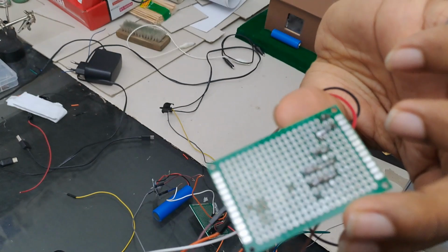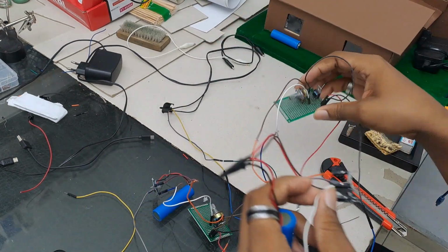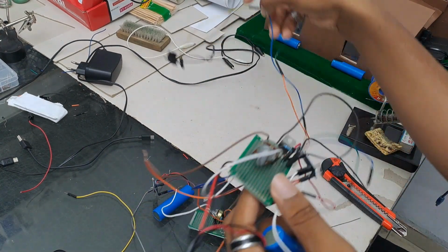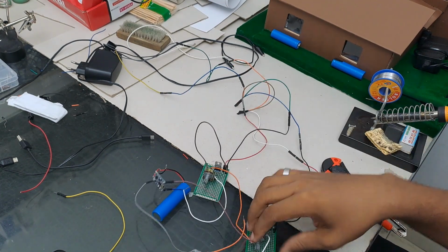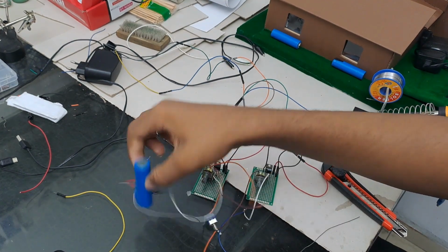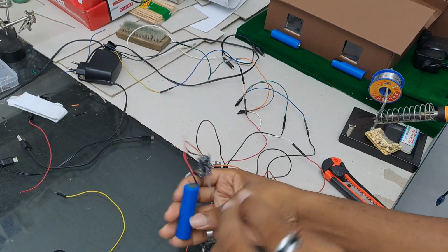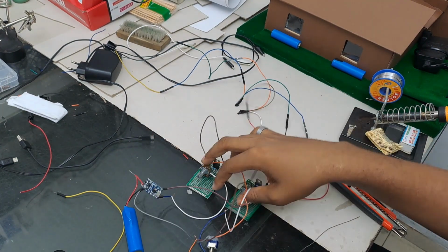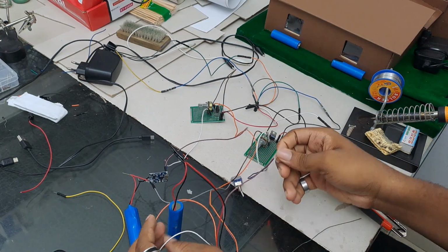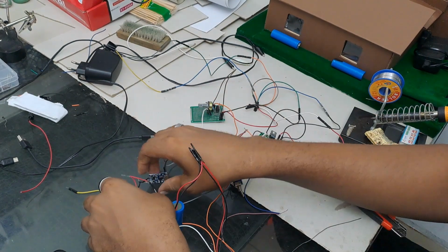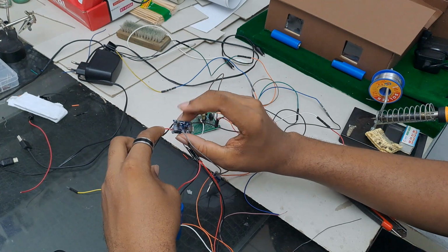But since everything is within the 5 volt and 3.3 volt range and should not be enduring any stress like an electric motor or a servo motor, where you would want your power externally supplied and your control pin to your Arduino alone, this functionality works where you only supply to your Arduino and then let all the current drain come from your Arduino. So that is how the system functionally works. That is the explanation for everything for the system.